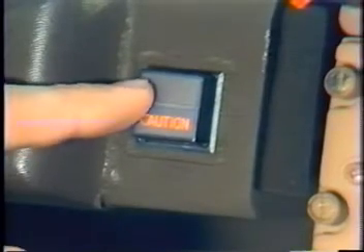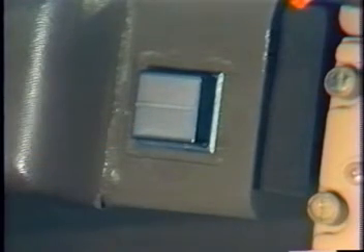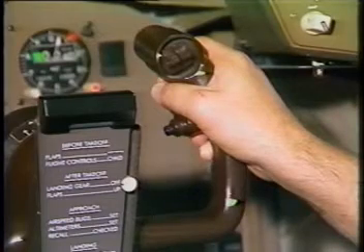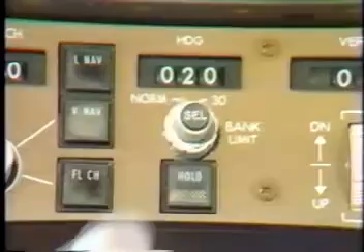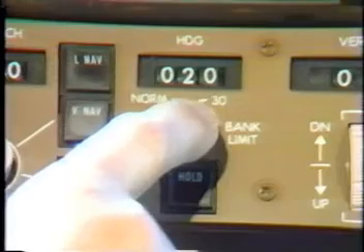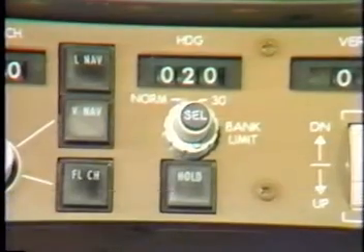Master caution lights may be canceled by pressing either lens cap. The remaining caution messages are removed by disengaging the autopilot, engaging a different autopilot mode, or if the failure is corrected.